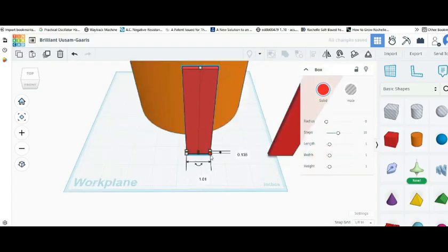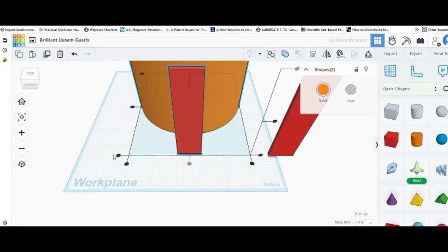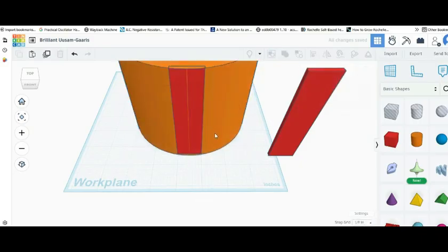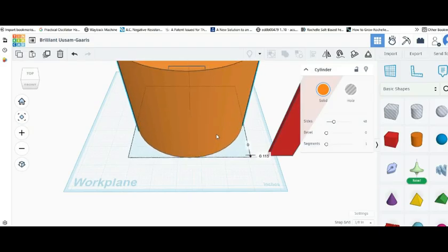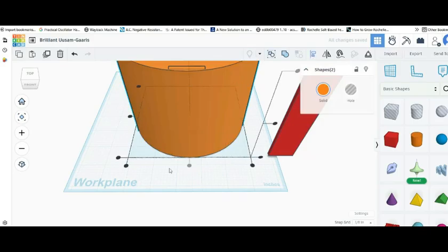Okay, what I actually did also here, even though the magnets are going to be 1 by 4 by 1/8, this is going to be the slot that they fit in. So I gave it an extra 1/100th of an inch and an extra 1/100th of an inch that way, so that the magnet will be able to slide into the slot. So the way this will work is line that up, and the grid is set to 1/8. So if we do one, yeah, that's the idea. One like that, and then make sure everything's lined up. It still is. Then you would hit kaboom.